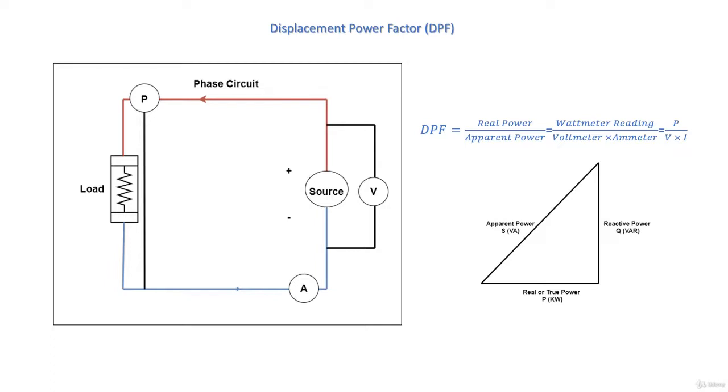The software does it automatically if you let the software suggest an inverter, but why would I need to do this? In most countries, rules require you to supply reactive power, and to make the network stable, you have to establish balance between the PV system and the network. If a network charges only for a power factor of 98% and you have to work on a 98% power factor or pay for a penalty, then 98% of the apparent power of the inverter can be used as real or active power. So you need 2% more power to supply the reactive power.